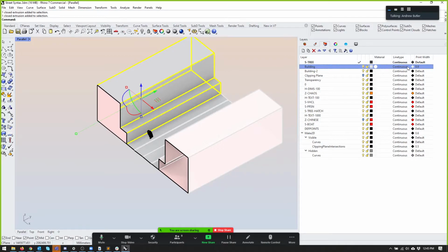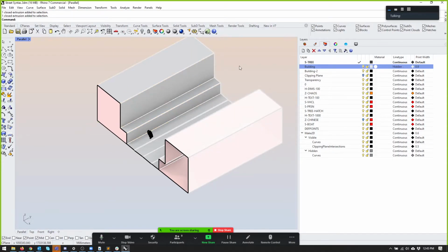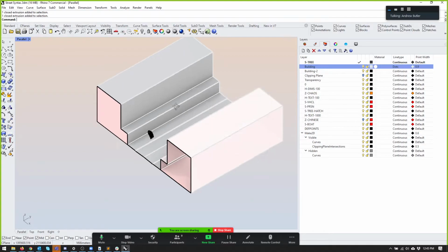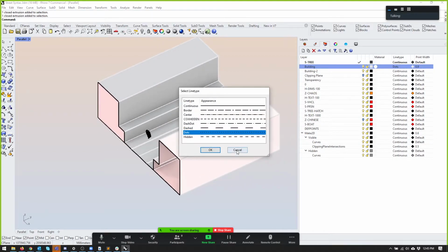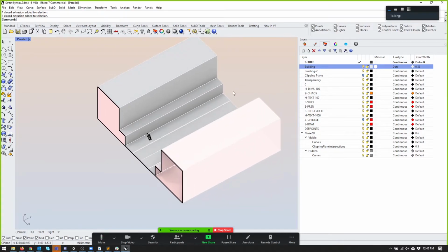What Rhino does is it tries to map the widths to a rough truncation of line weights. So in the line weight specification dialog that Leo had up, rather than picking a number, you're probably better off just picking what visibly looks like the right weight that you want, and that will show up as that weight in the display port.